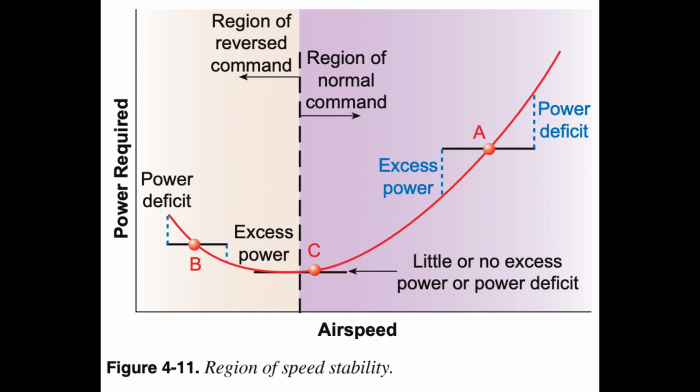Climbs. The ability for an aircraft to climb depends upon an excess power or thrust over what it takes to maintain equilibrium. Excess power is the available power over and above that required to maintain horizontal flight at a given speed. Although the terms power and thrust are sometimes used interchangeably, erroneously implying they are synonymous, distinguishing between the two is important when considering climb performance.